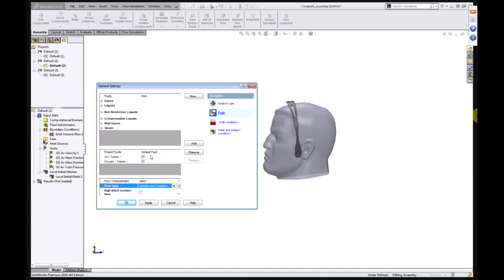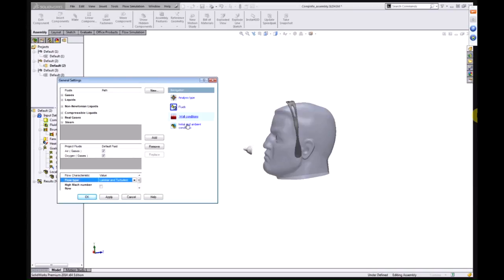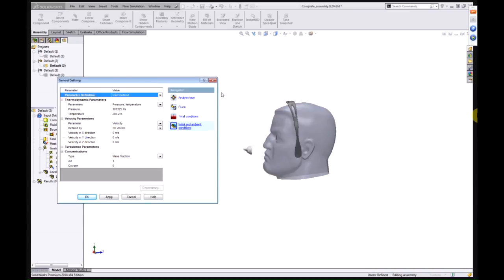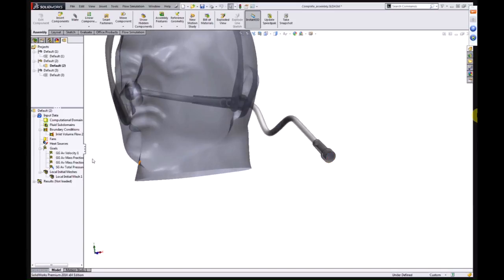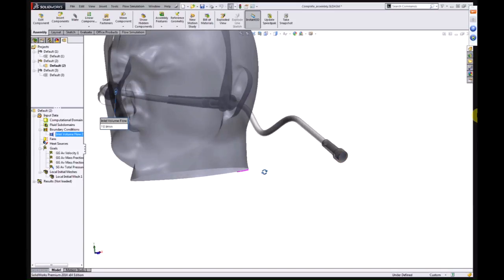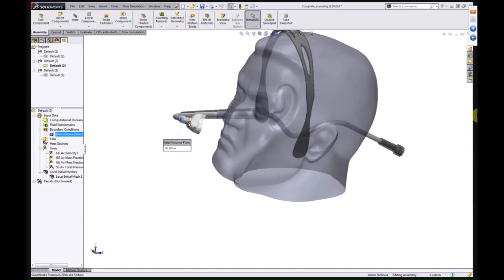We have a flow source at the delivery point to the little oxy-arm here, where we're providing 10 liters a minute of flow, and we are providing that as 100% oxygen, pure oxygen. Now, you don't want to deliver 100% oxygen to the patient necessarily for long-term care.